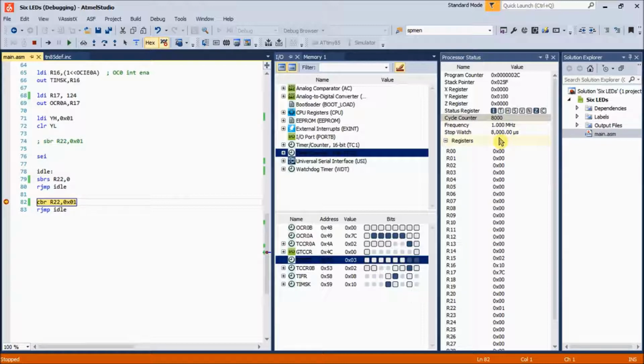It's trying to do it every 1000 milliseconds, but something is taking a little bit of extra time. There's an extra few cycles being used somewhere. It's probably because the jumps are 2-byte instructions. But you can see that if I hit this 100 times, it'll be very, very nearly 100,000 microseconds.